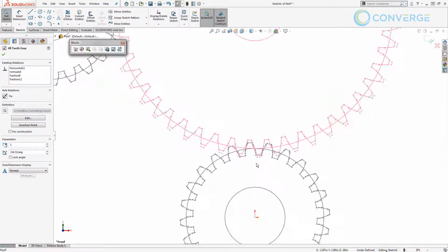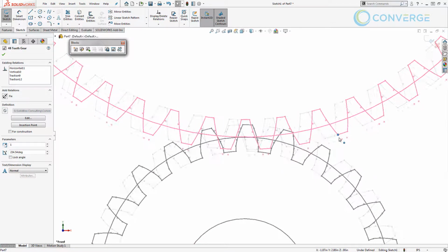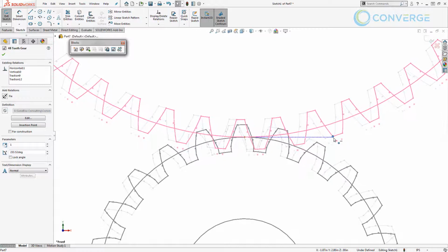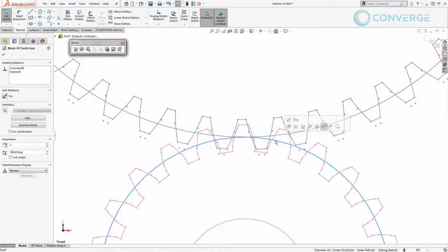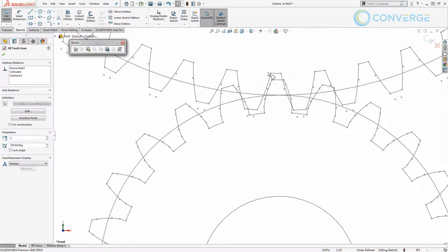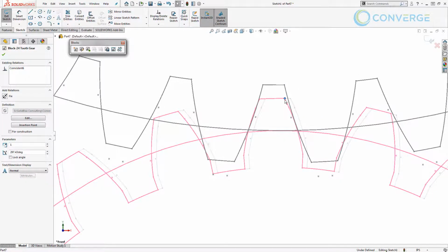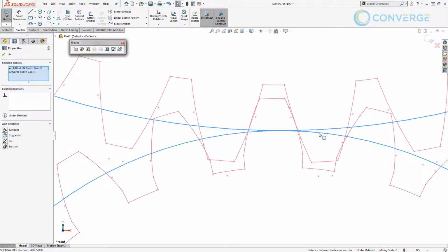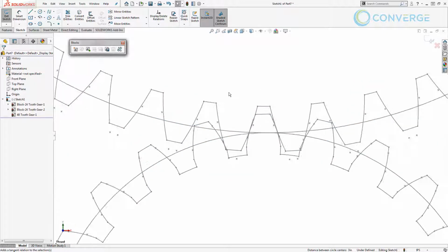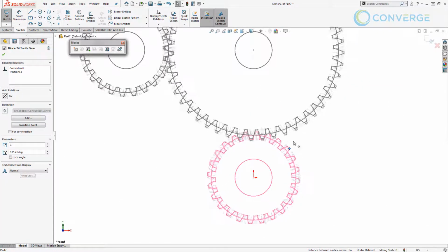So there is some functionality and some orientation that we need to be careful with, but you can see in this instance that the gears slightly are overlapping. So I'm going to select this circle over here, and I'm going to find the constraint for engage, select it and delete it. Then I'll rotate this instance, and once I'm happy with its position, again I'll select those 2 circles, I will engage, and then we'll OK that. So now as I turn one of these gears, all of them turn, right?